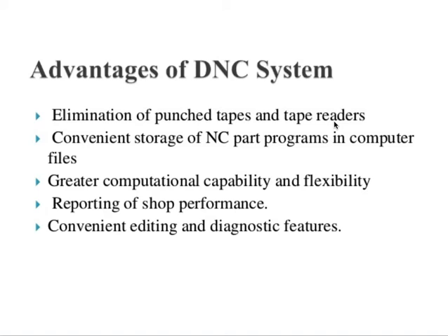It allows convenient storage of NC part programs in computer files, and it gives greater computational capability and flexibility for such functions as circular interpolation, reporting of shop performance, and convenient editing and diagnostic features. There is also time sharing, or the control of more than one machine by the computer. And last, we can say the remote computer location: the computer is located in a computer-type environment only.